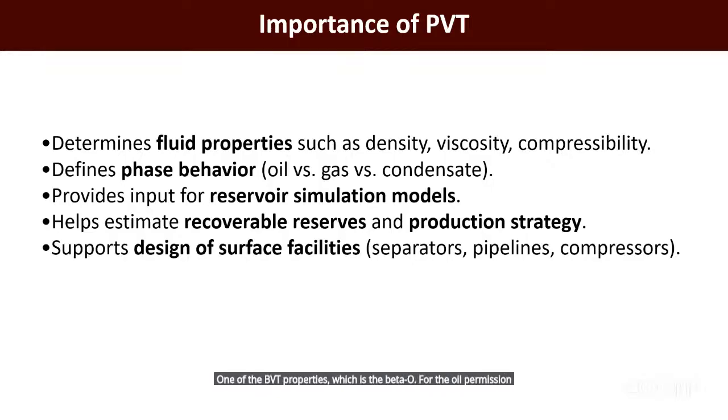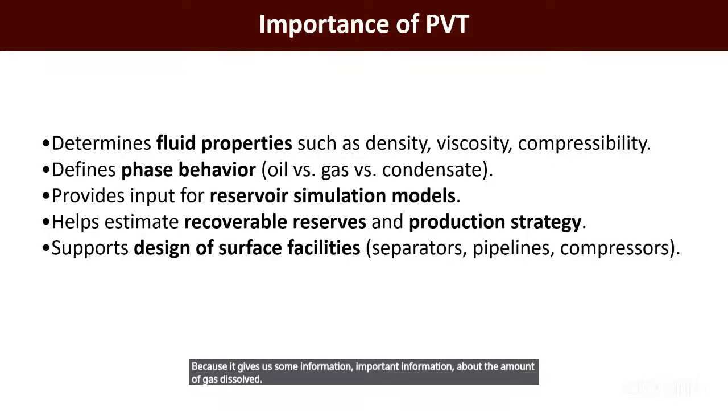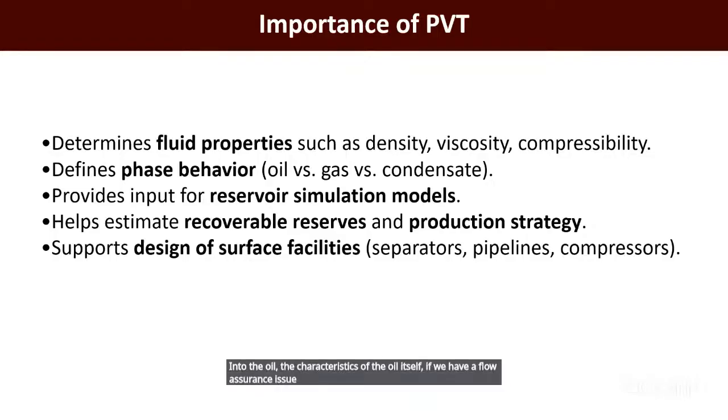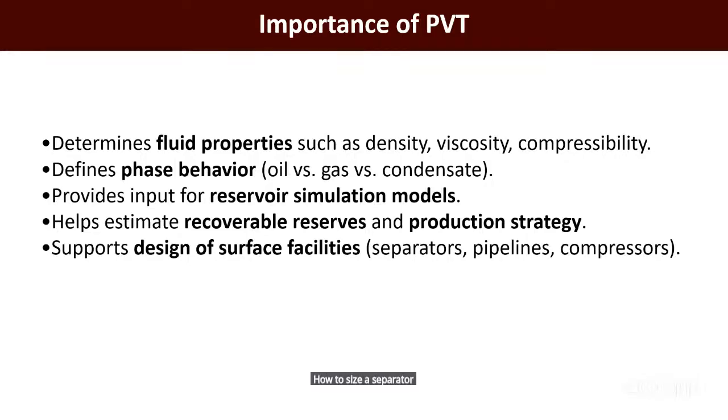Also, it's important to design the surface facilities like separators, pipelines, and compressors because it gives us important information about the amount of gas dissolved in the oil, the characteristics of the oil itself, and whether we have a flow assurance issue like asphaltene, wax, or hydrate formation in gas reservoirs. Also, it's very important to understand how to size the separator based on the gas oil ratio and the composition of the gas itself.